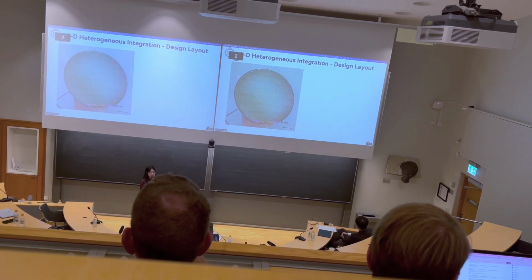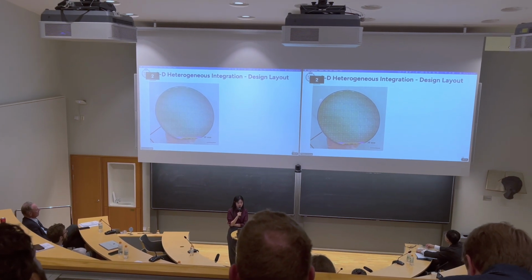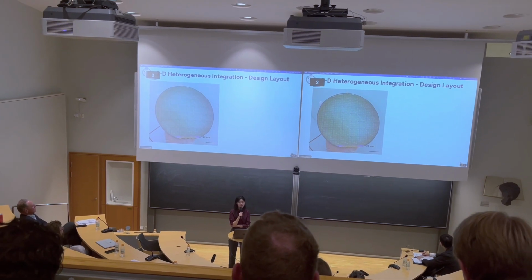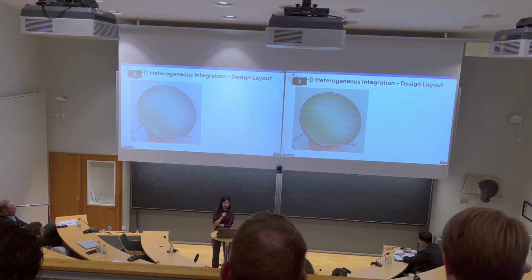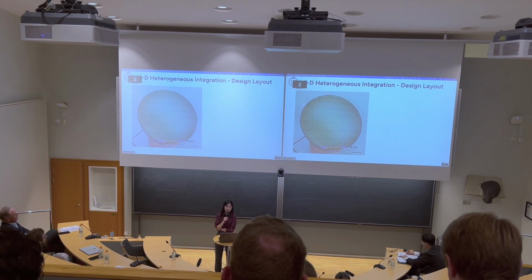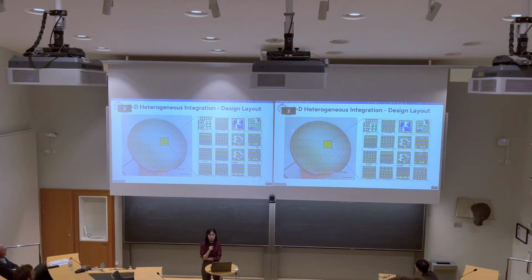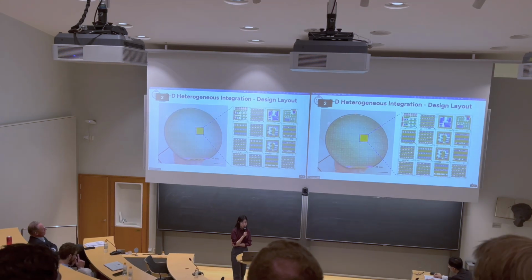So this is a 6-inch wafer after the bonding and removing the handle layer. And before we continue for the rest of the post-foundry process steps, we dice it into smaller chips, which is 2 by 2 centimeter. And for each of the 2 by 2 centimeter chip, we have a 4 by 4 array of different designs, which has 16 subchips.